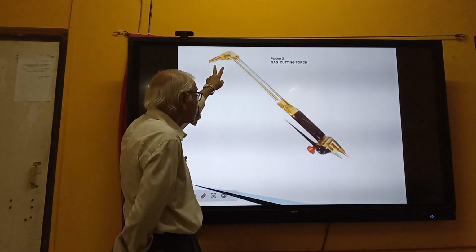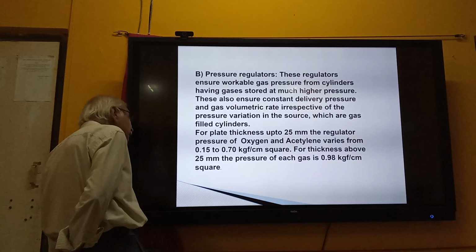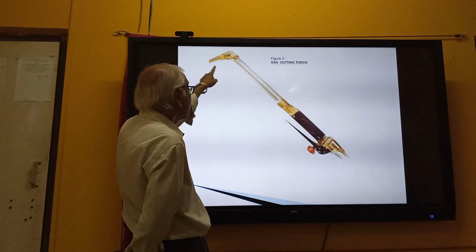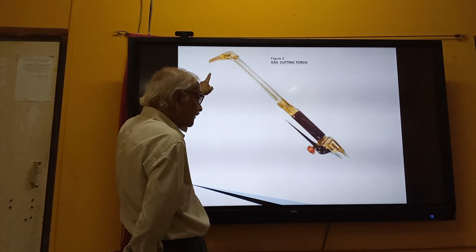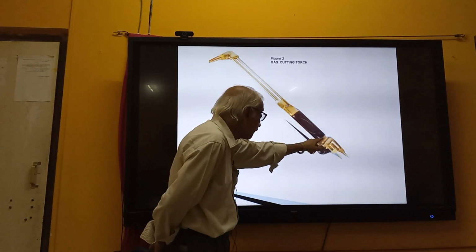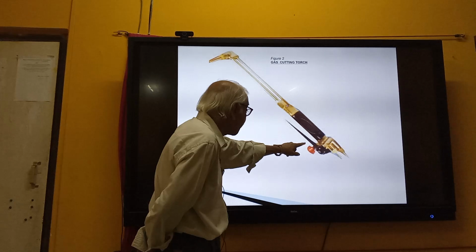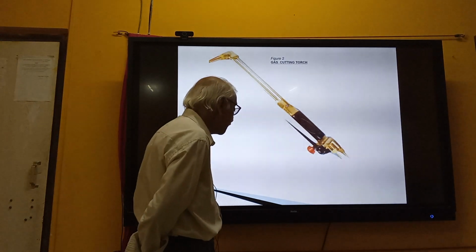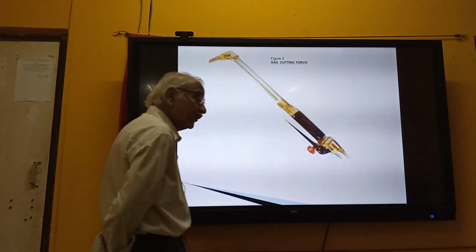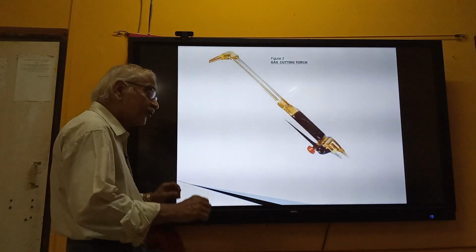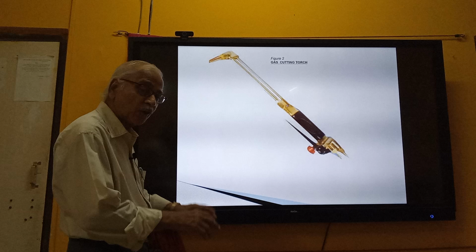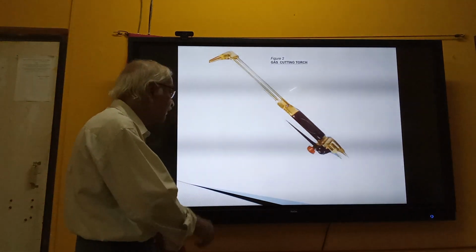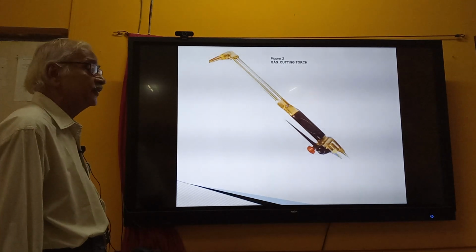The nozzle tip is a little smaller, and there is an extra pipe for the high pressure oxygen gas to be injected separately for gas cutting. There are two inlets again, but the gas comes here, and the high pressure gas actually comes out when this particular lever is pressed. So normal blue and red lever, they will supply normal oxygen and normal acetylene to form the flame, but when you press this particular lever, then extra oxygen supply will be there and cutting action will take place.